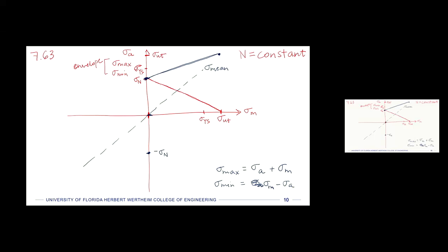I'm going to go from this bottom line here, draw the same and go all the way up. You can see now that the mean line falls directly between the other two. So this is now our window of min and max for some stress amplitude. It's the beginning of our envelope.